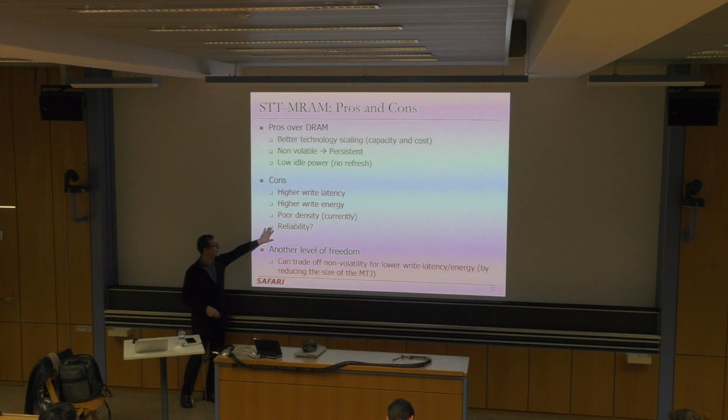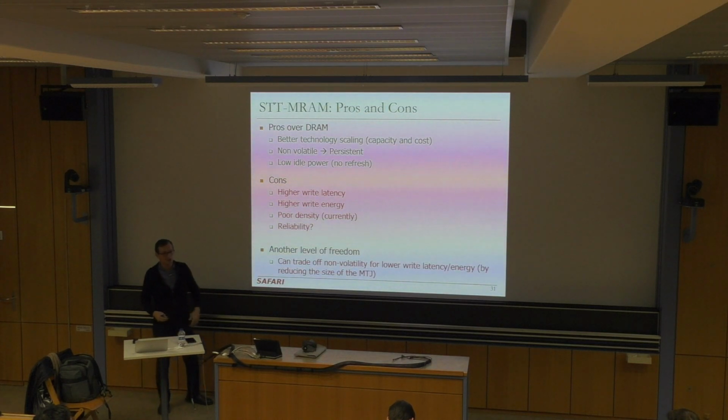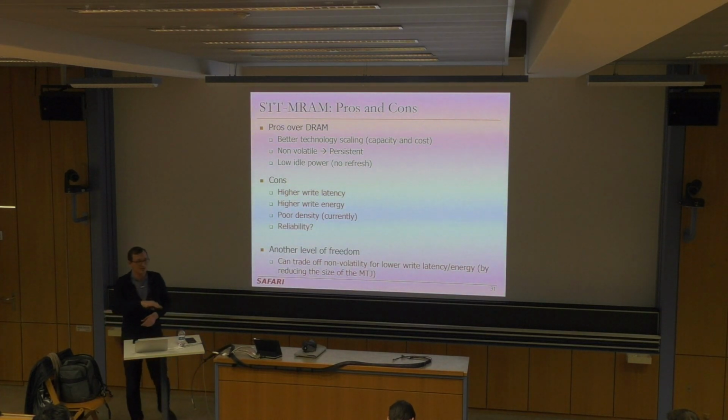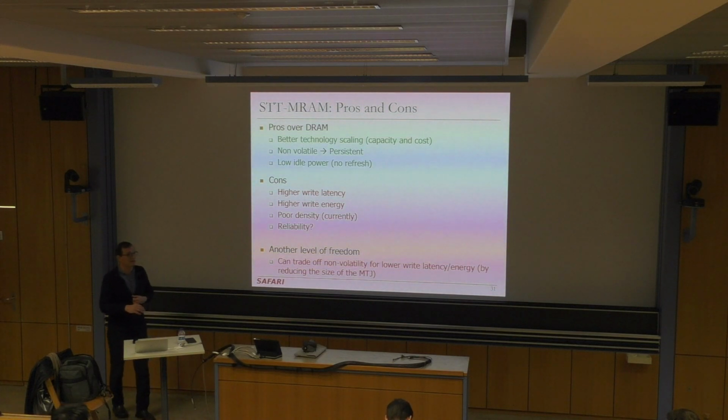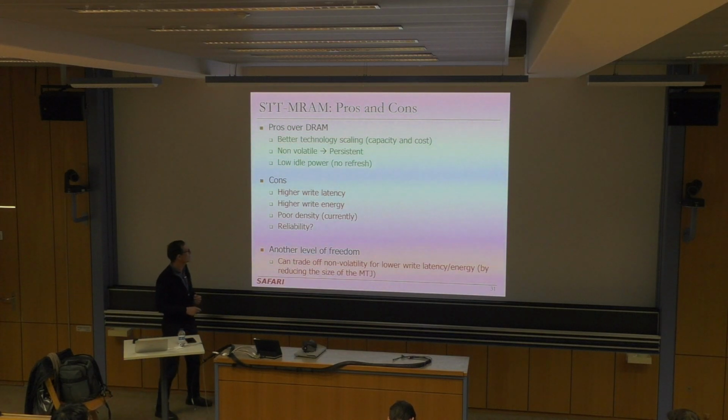We're not going to talk about this, but there are, for example, reliability issues in terms of write disturbance also over here. And sometimes you get write errors or read errors. If you don't actually push the current in a nice way, you may not be able to change the magnetic orientation of the free layer. As a result, you get write errors, right? You may not be able to write the data correctly into the device. And those need to be solved somehow.